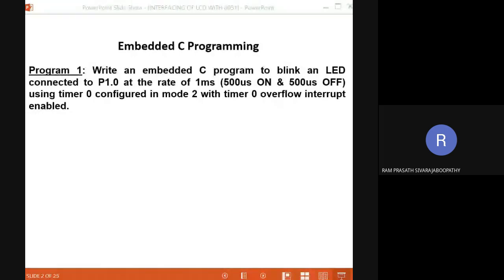I put the word format of the TMOD register. Kindly help me out. What should I write? I am speaking about timer 0. Only the lower 4 bits we have to consider; the upper 4 bits should not get disturbed. First you tell me the word pattern we have to write for the lower 4 bits. Obviously, we are not going to use gate control.